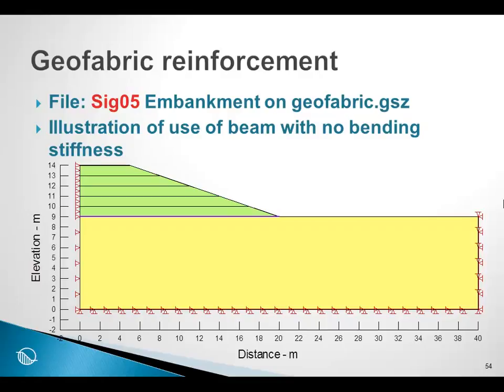Now we will use a beam element to simulate the effect of a geofabric. A geofabric can withstand tensile force but no compressive force, and the impact of the tension in the geofabric will alter the stress state in the ground underneath an embankment, for example. The other thing is that in this particular case here,